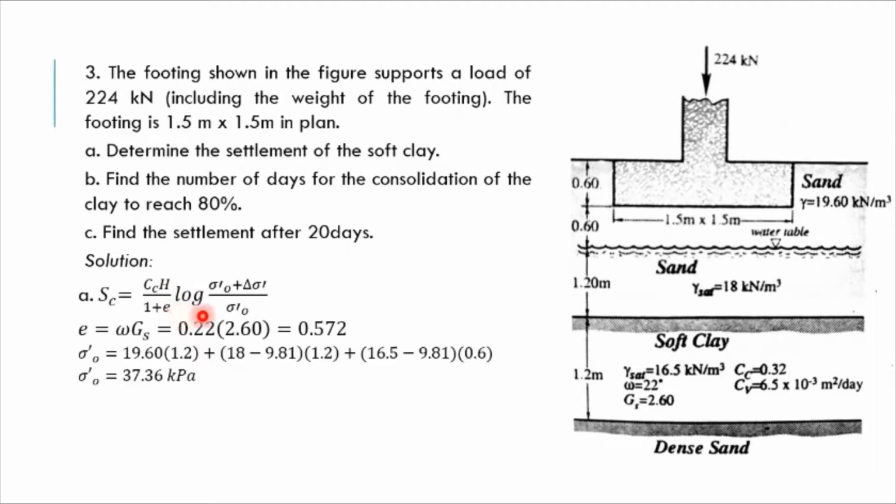So we already know C_C, H over 1 plus e, and the logarithm with the overburden pressure. We have to know the value of the change in stress. Will it be just equal to 224? Actually, the answer is no.